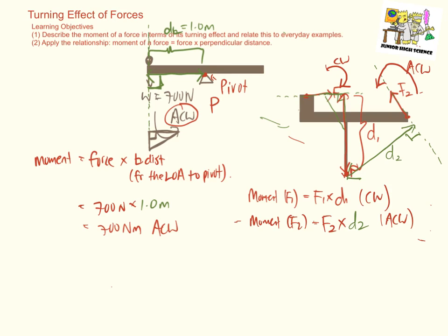Ultimately, what will happen to this structure? Will it rotate in a clockwise direction? Will it rotate in an anti-clockwise direction? Or will it not rotate at all? It depends on how these two values compare. If the clockwise moment is bigger, then the whole structure will rotate in a clockwise direction. If the clockwise moment is exactly the same as the anti-clockwise moment, then the structure will not start to rotate. That's it for today. I hope you have learned something about the turning effect of forces.